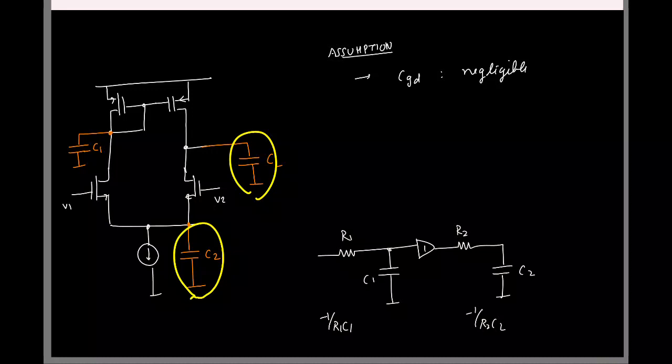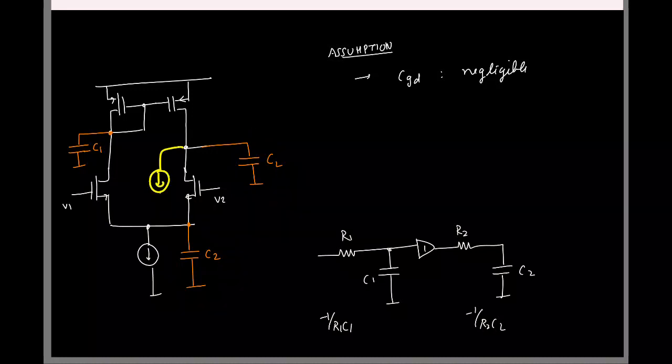Current source? No, okay. See, current source is fine because this is an ideal current source. I can say that the current source is also coming from anywhere to anywhere. This can even be floating. This will still pump in a current. The point is, when I mean coupling, you will have current flowing from one node to the other. The current source is not pumping in a current from this node to this node, right? So is there something else that can introduce coupling?